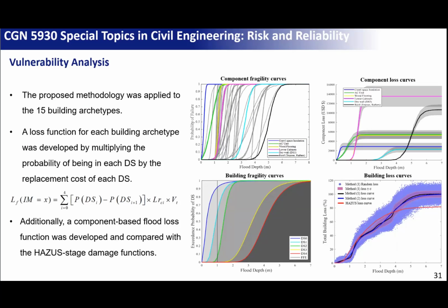And this is the fragility curve for each component, like 65 fragility curves. And as you can see, here at 1 meter, we have most of the fragilities of the appliances, like fridge, stove, washer, dryer. We have lots of fragility at 1 meter, because at 1 meter you have almost all the components in your apartment, like tables, furniture, most of the appliances, most of the gadgets, lots of things. But here, you'll start to see damage to the drywalls, and then damage to the walls, the framing, the ceiling, the roof shingles, and all the other components. The second step is to convert this damage to losses, right?